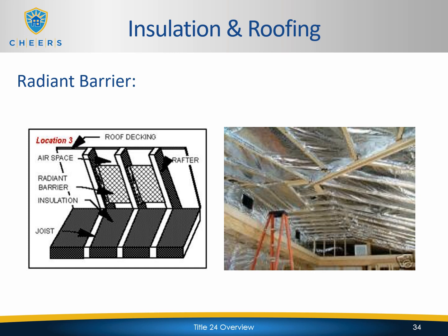This application is more of a retrofit approach. It's actually used a lot in retrofit applications. I've also seen it used where the builder is supposed to put on a radiant barrier and they somehow forget, so they have to go back and put it on after the fact. But basically, it's the same type of material found in the second example that I showed you. The difference is the fact that the roof sheathing is already installed in this scenario. They just go back and basically fix pieces of radiant barrier below the actual roof deck around the trusses, and they staple it directly to the framing members.